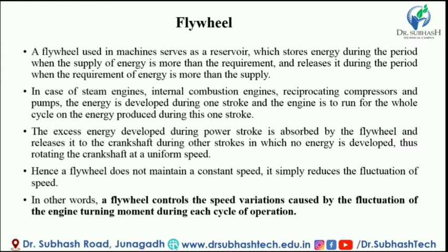In each cycle we know that only one power stroke is there and in the other strokes no energy is developed. A higher amount of energy is generated in one stroke, but in another stroke no energy is generated. So this fluctuation is reduced by the flywheel. I hope you understand why the flywheel is used and what the work of a flywheel is.